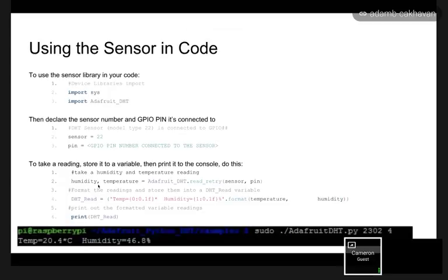And in this case, the company told me to use their sensor by first storing their humidity and temperature sensor readings in a variable by calling this specific Adafruit DHT read entry function call. And once it does that, then you could format the data in a certain way like this and print it out to the screen. If it works, if it is actually printing something, that's usually a good sign. And if it's not displaying like 1000 degrees Celsius, I think you're in good shape and you could trust that the electronics work and continue coding with the rest of your project.